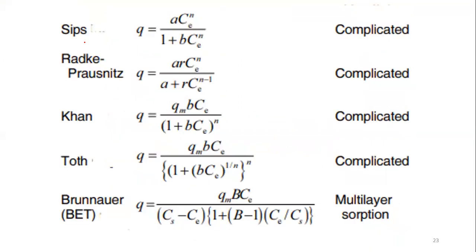It's quite useful. You also have other, more complicated models, like the SIPS model, which basically tells us what the adsorption is. In the case of Freundlich, Langmuir, DR, and Temkin, they are quite straightforward and interesting: either it is monolayer, multilayer, or a temperature effect. But in the case of the SIPS model, it's really very complicated. The mechanism is complicated. We cannot say that it is a monolayer-dominant or multilayer-dominant mechanism, complete or non-complete coverage, physical or chemical. It's a complex type.